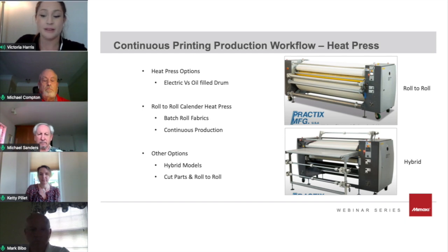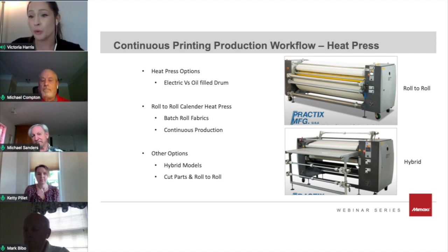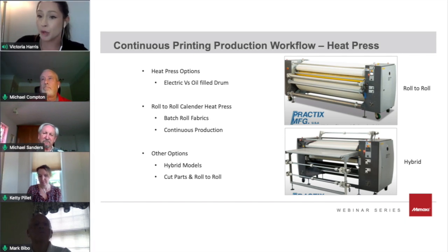Oh yeah, I did want to mention for electric versus the oil drum heat presses, you have more heat consistency with the oil filled drums versus the electric. Electric systems are still good technologies, but when you want to go with more of the high quality or grand format printing technologies, you might want to be looking at an oil filled drum heat press.